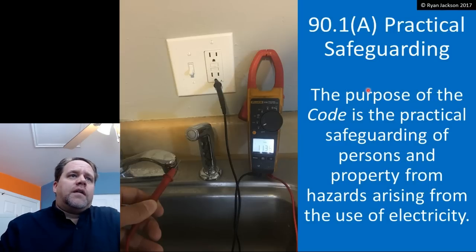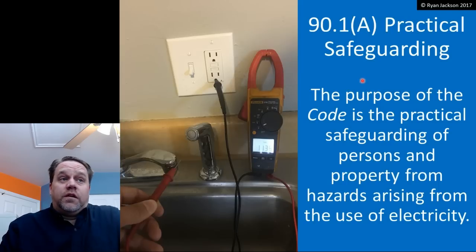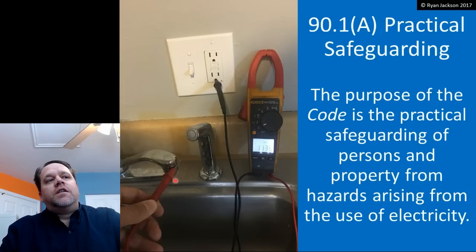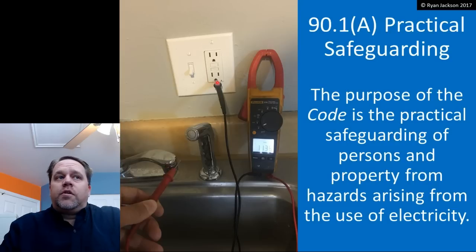That's the other thing that we're trying to prevent. Now, this photograph seems unusual, and it certainly is, but it's real. It's not a staged photograph. This is a real installation, and we're measuring 113 volts, so essentially 120, from the metal parts of the faucet to the equipment grounding terminal on this receptacle. So anybody touching this could receive a fatal electric shock, and that's what the code's trying to prevent. This is not a code-compliant installation. In a code-compliant installation, you would never have 120 volts between the faucet and an equipment grounding conductor.